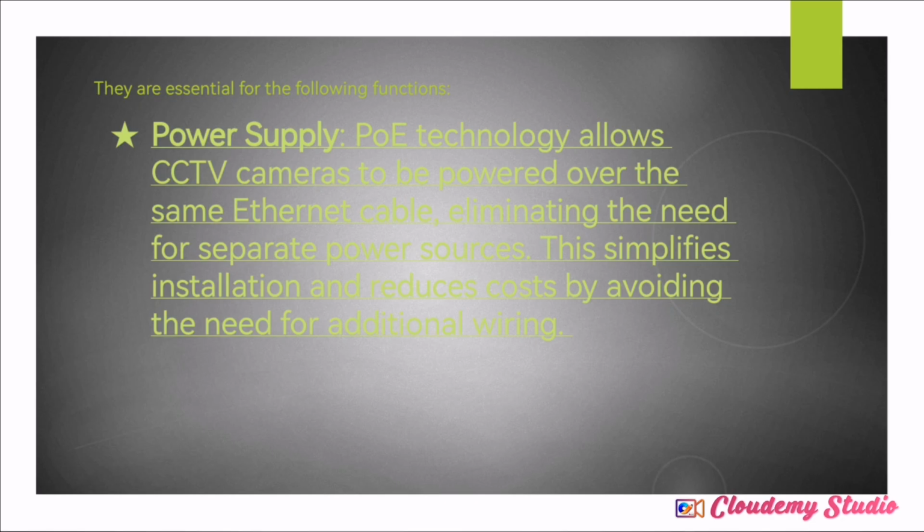With a non-PoE switch, even if the camera is PoE, that switch doesn't have the function to supply power to switch on the camera, but only to transmit or receive data from the camera, meaning you still require a charger connected to the camera in order for it to start recording. Let's proceed, please.